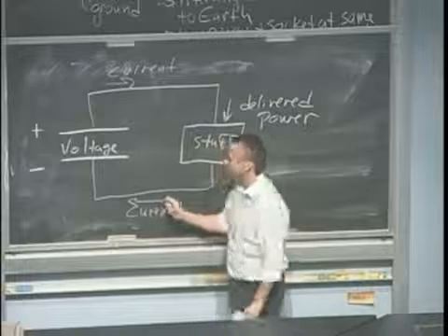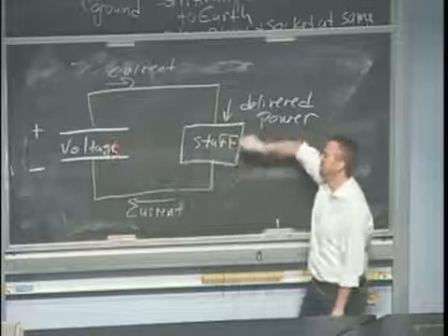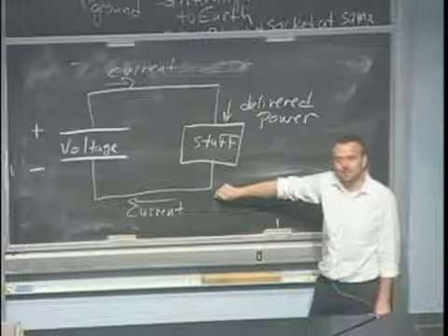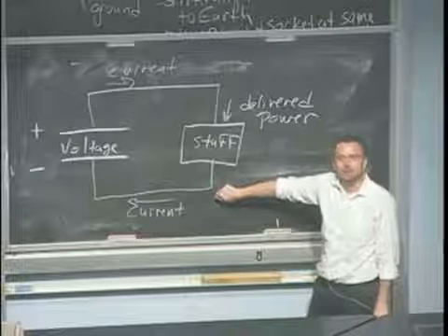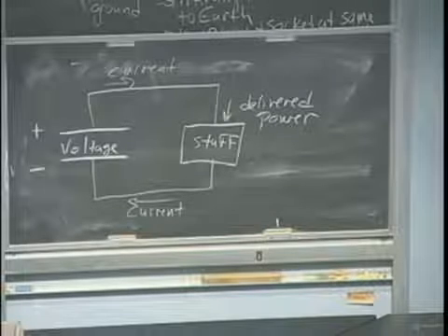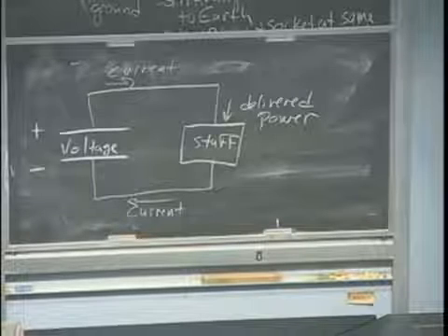Wow, you anticipated my next topic immediately, which is, in all of these previous pictures, we basically ignored any resistance in the wires. We had all the energy being transferred to our appliances, and we ignored the fact that the wires themselves have some resistance, which means that there is a voltage drop across them, which means that there's power being dissipated in the wires. And we just saw that dramatically here, where we saw the power being dissipated in this little section of wire, but power was being dissipated all throughout this system. Make sure I turn that off.